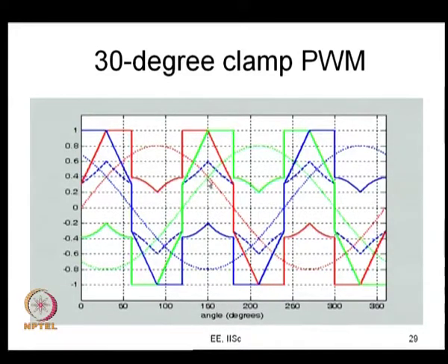In the middle, you are still following the positive common mode component. The positive common mode component now basically comes from here. So, the positive common mode component is the difference between Vp and this signal, and so the next phase, Y phase, gets clamped for 30 degrees now. So, here R phase is clamped to the positive bus for 30 degrees and here again for 30 degrees. This is between angle 30 to 60 degrees and this is between angle 120 to 150 degrees.